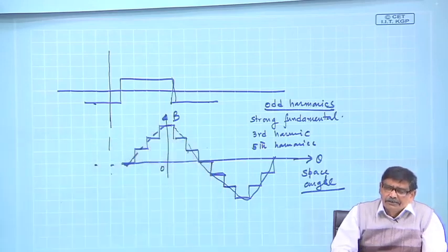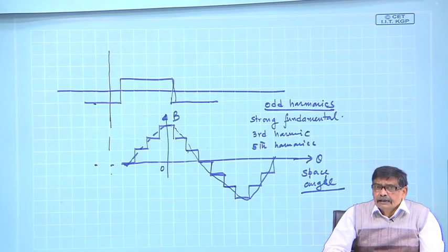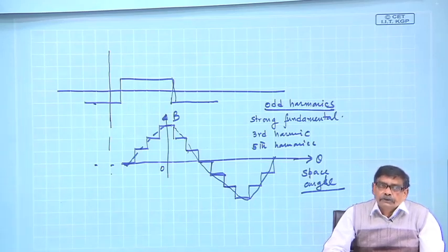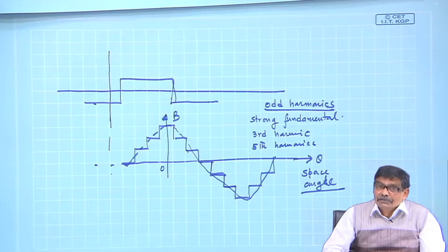How many distributed coils depends on the amount of space available, then you can use the coil span as a variable to see that a particular predominant harmonic is eliminated. Then we have won many things.